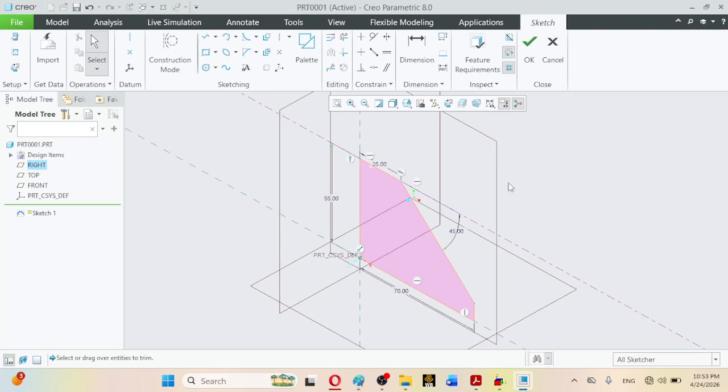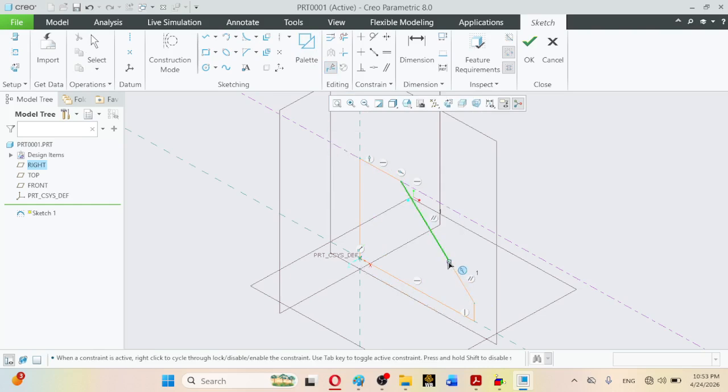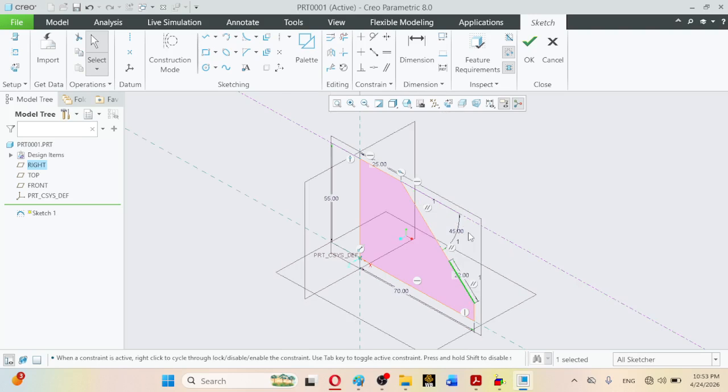And after that, how will we create it? The best way that you can adopt is, for example, to use this divide command, so you can simply click on two random points here, at an approximately suitable location. And now you will be dimensioning this line to be the same 22 units like this.